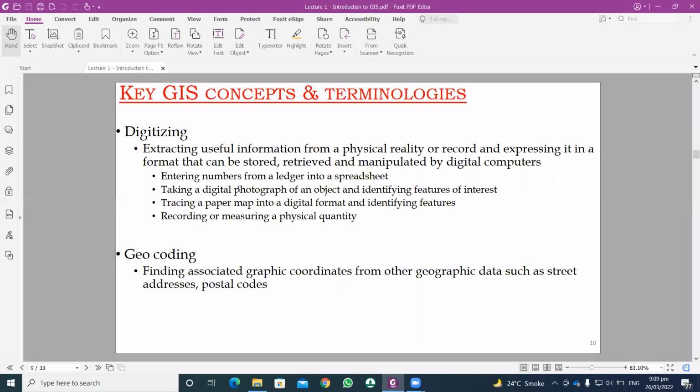So what we will do is create junctions and pipes, converting the physical reality into a model, and then we will give the information related to it. For example, for a junction, we will assign elevations, and for a pipe we will calculate the length of these lines. So practically, when we draw a model spatially in a GIS, we will use a spreadsheet, an attribute table.